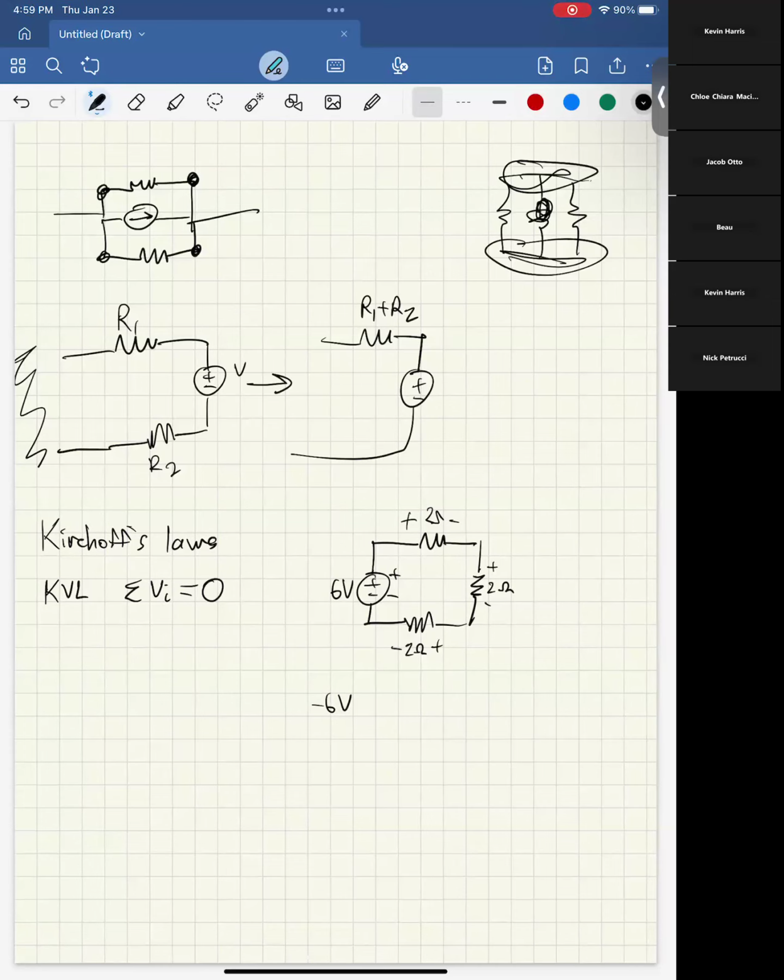So here, a better example of this, to make the numbers a bit more clear, would be like this is 9 volts. Since all three of these have the same resistance, all of them would have a voltage drop of 3 volts. So for this example, we're saying around this loop, and around any loop in any circuit, this will apply.